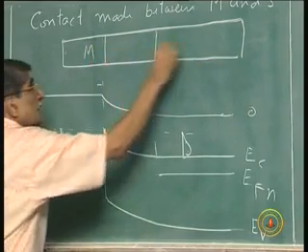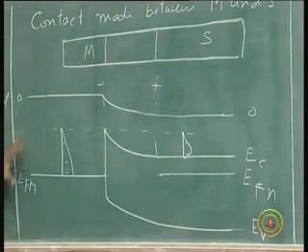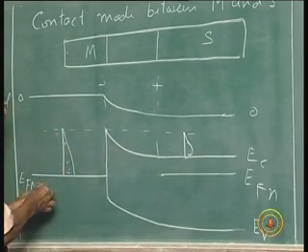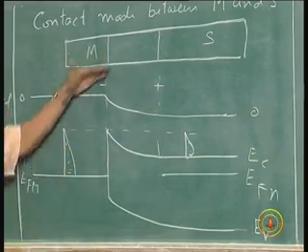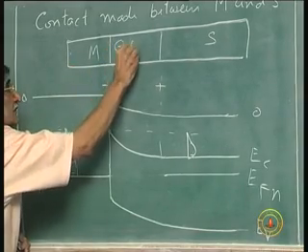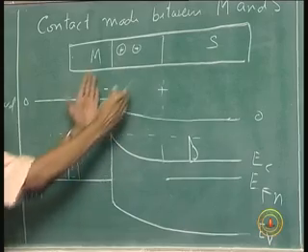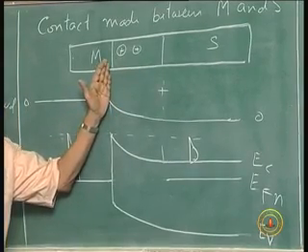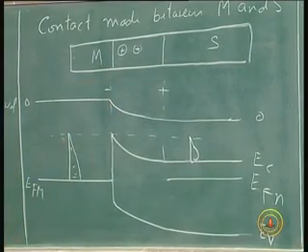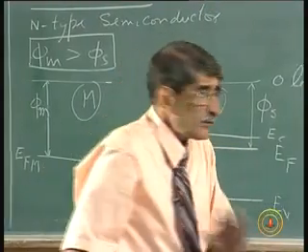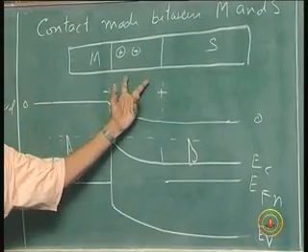So, the metal and semiconductor, because this diagram comes only here. Now if I apply a reverse bias, this is thermal equilibrium conditions. The voltage can appear only across this, because in the metal if there is a voltage there is large current flow, well, electron concentration is very large. So it is not going to appear across that, it is going to appear across this portion.